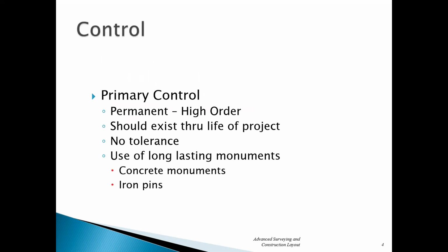So primary control is essentially what we were establishing. That's your permanent kind of stuff that has to last throughout the whole project. And so that's what I'm having us walk through. And actually, when we get out and start dealing with our labs out in the front yard of the school, I have a control network out there that we would consider primary control. It's a pretty high order. It's been there for years at this point, and so we're going to see how that works and how we use that.